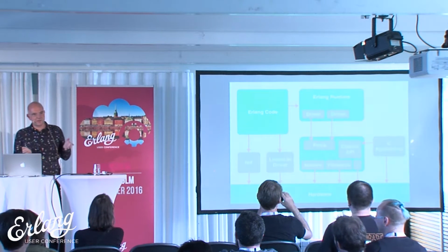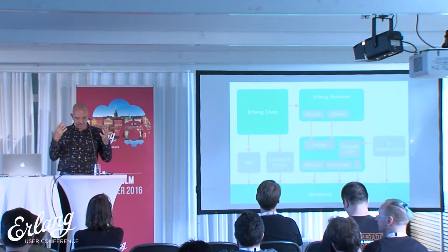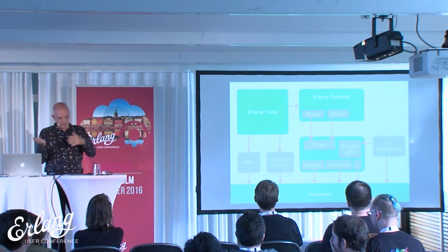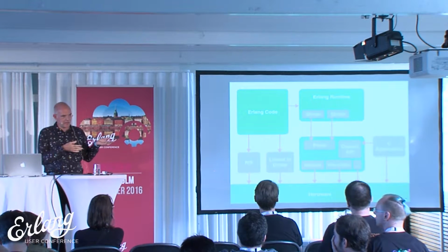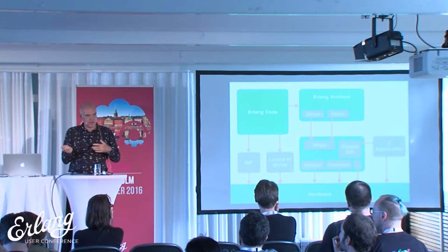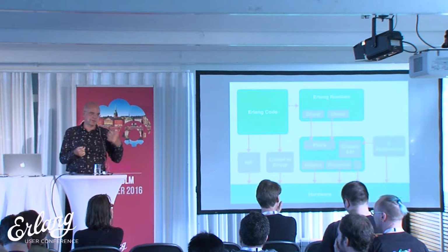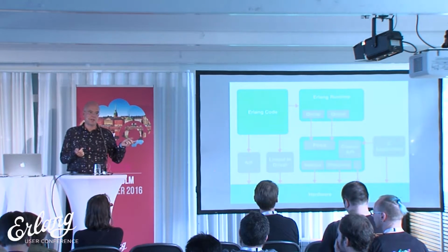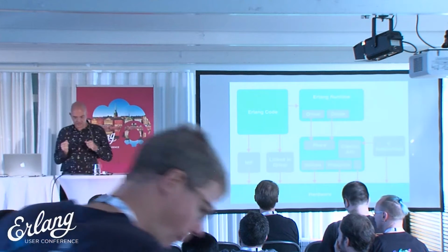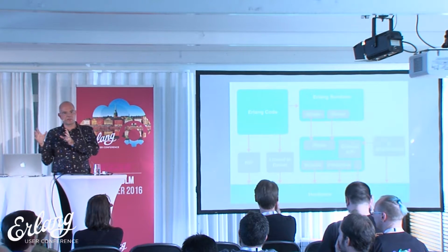So the architecture of the whole setup: you have the Erlang VM on RTEMS, you have your Erlang code that runs on the Erlang runtime, and the Erlang runtime uses the POSIX API to actually talk to the hardware and to use, for example, the TCP/IP stack of RTEMS. We actually have a choice of 3 TCP/IP stacks, from very small to the current FreeBSD TCP/IP stack with SMP support. You can add to this another application written in C.